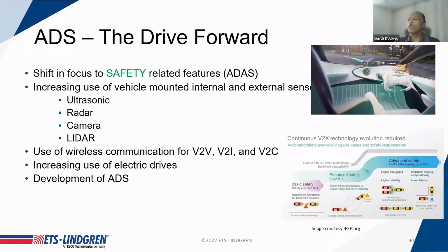Now, V2X communication is just one aspect of the measurement. Another one is the use of advanced driver features, where those features, again, use some components that rely on over-the-air propagation. Radar is one of the examples that's used in quite a lot of the adaptive cruise control and autonomous braking and detection features. LiDAR is another one that's used, not necessarily what we would consider in the traditional sense of RF. And then cameras is another one of the sensors that's used.